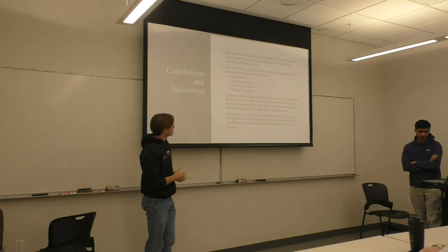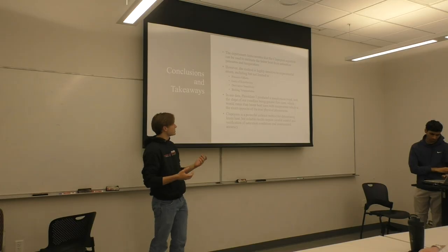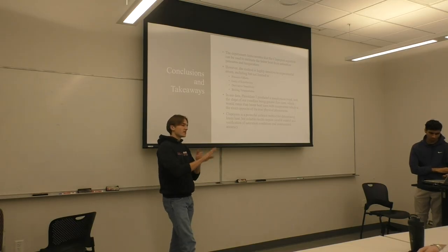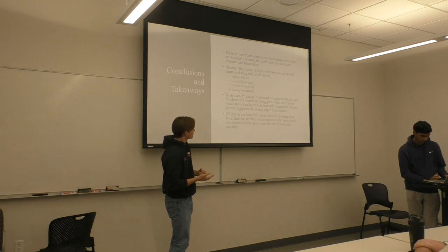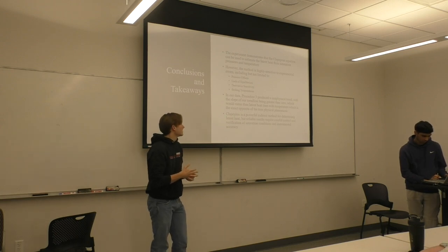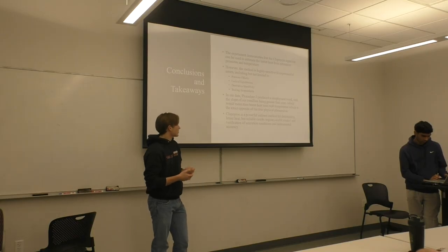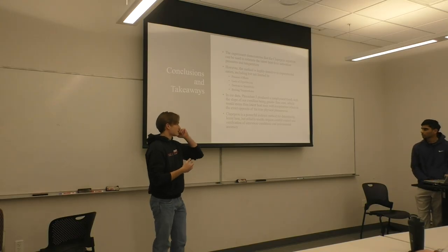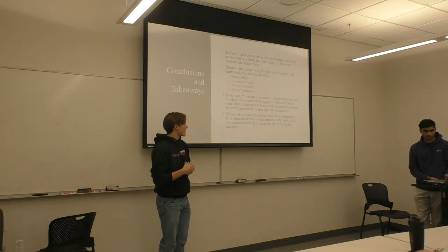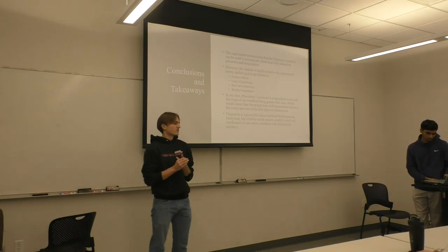Boiling temperatures as well. And the final conclusion is that in our data, procedure 3 produced a non-physical trend, with the slope of the trend line being greater than 0, which would mean that latent enthalpy rises with temperature, which is non-physical. But overall, Clapeyron is a powerful indirect method for determining latent enthalpy, but reliable results require careful calculation, verification of saturation conditions, and instrumental accuracy.